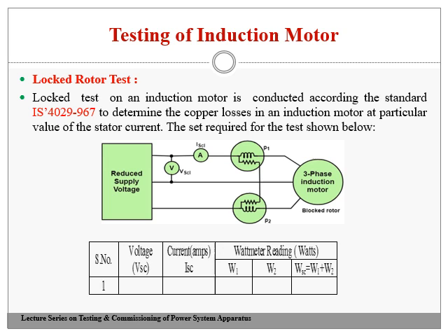Before conducting the experiment, the induction motor rotor is locked with the help of a brake drum arrangement, and the 2 wattmeters are connected as shown in the figure, with the ammeter in series with one of the lines and the voltmeter across the 2 line terminals. All this complete setup is connected through a 3-phase auto transformer.